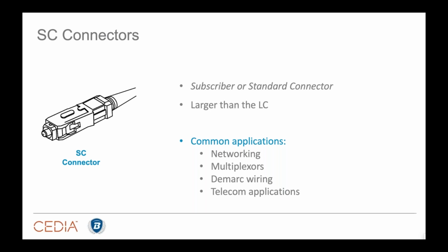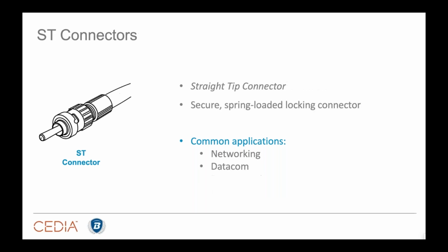Now, LC and SC style connectors terminate in the same manner. So this is something you want to keep in mind, and we'll talk about this here in a minute. What tools do you use? What's the process that you use? Well, the good news is if you can terminate an LC, you can terminate an SC, and vice versa. The same process, the same tools really hold true. These tend to be universal style connectors. They're pretty easy. Takes you about a minute to a minute and a half, depending on the type of cable that you're using. We'll talk more about that, but let's get through our connectors first.